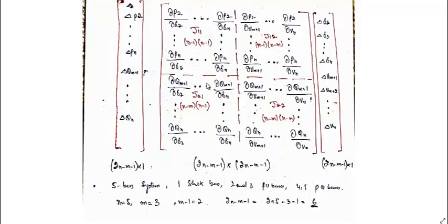So what will be the order of this matrix? We can get that order from this. The order will be simply the number of variables multiplied by the number of variables. The total number of variables for this system will be: deltas will be 4, that is delta 2, delta 3, delta 4, delta 5, and voltage magnitude variables will be V4 and V5. That means there will be 6 variables, and equations will also be 6, which we have already discussed. So the order of the Jacobian matrix will be 6 cross 6.